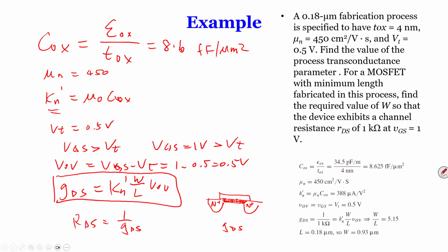But you say here that VGS has to be greater than VT, but in the earlier example, you said that VDS has to be greater. No, VDS has to be larger than VOV, in order to be in saturation. For the MOSFET to conduct, VGS has to be larger than VT. The difference is called VOV. What about VDS?